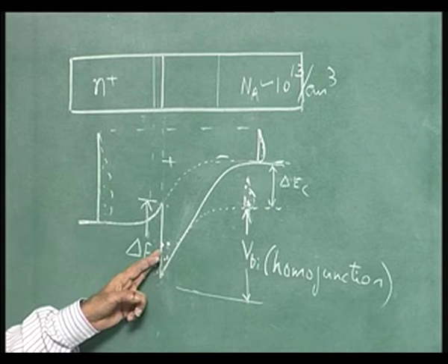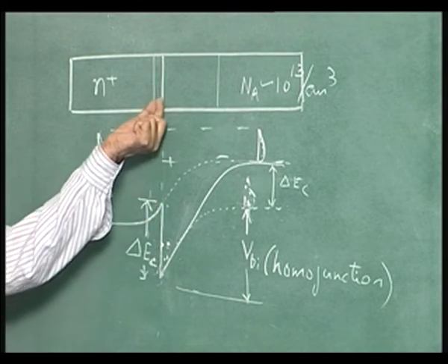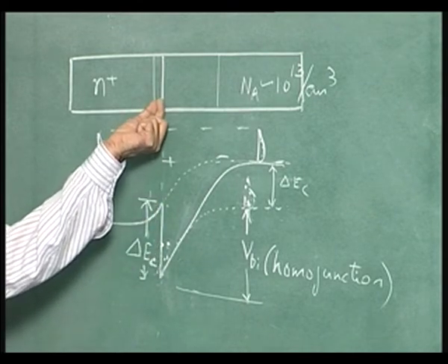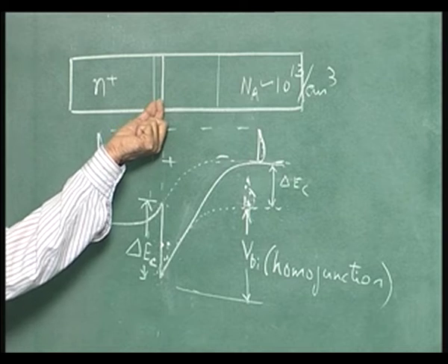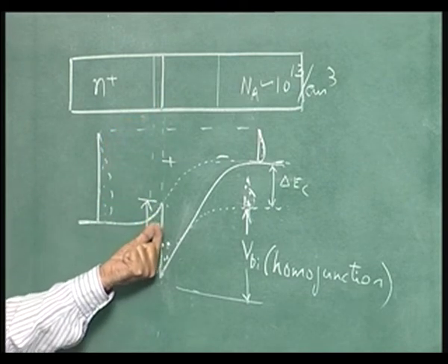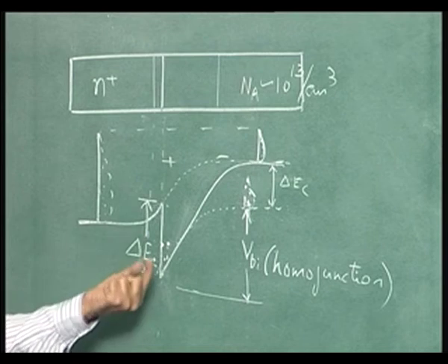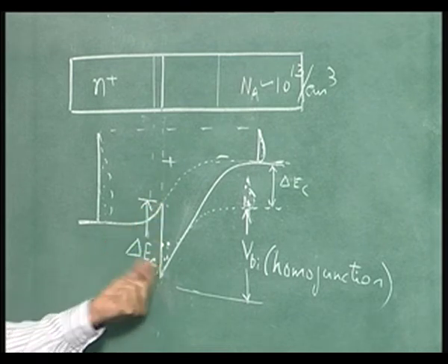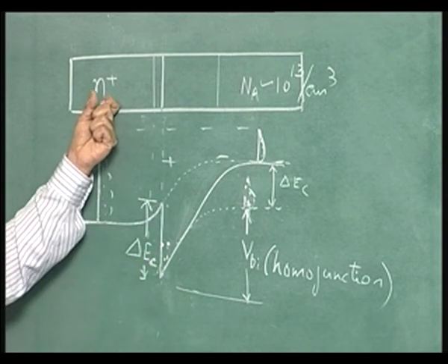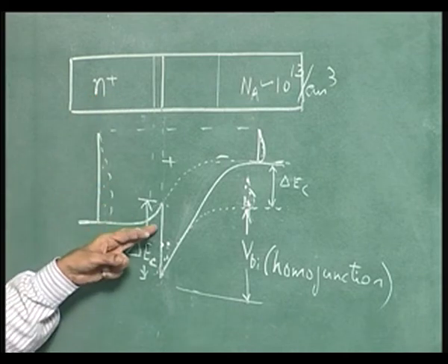So, what you do is you put a thin layer of 20 angstroms, 20 to 50 angstroms, usually 20 is the one that you put. Why we should restrict to 20 also will be clear when you see the transconductance of these devices. A thin layer you put which is not doped, but aluminum gallium arsenide. You need to put aluminum gallium arsenide only here to get this notch.